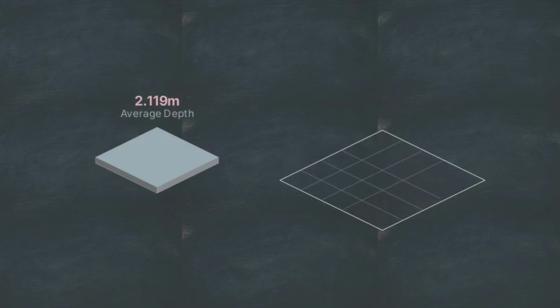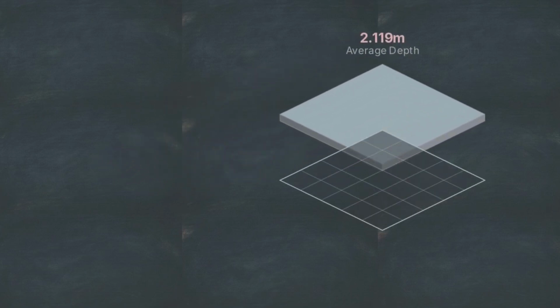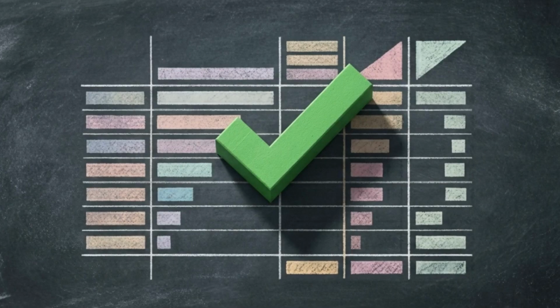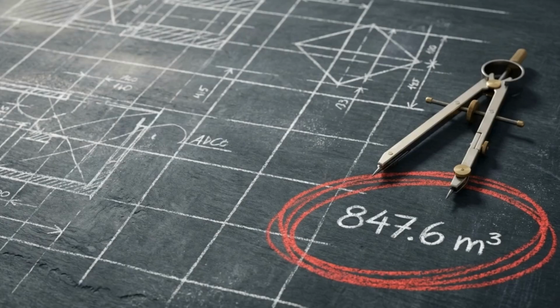Instead of repeating calculations, you multiply each spot height by its total number of uses. You sum those collective depths, divide by the total number of uses across the board, and multiply that single average depth by the entire site area. This collective calculation eliminates redundant math, drastically reduces your chance of making a spreadsheet error and gets you to the final volume in a fraction of the time.